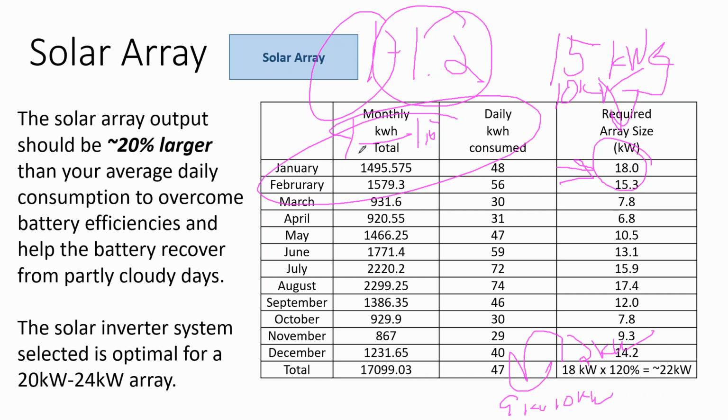And so, substantially, unlike with a batteryless system where the solar array is about 20% larger than the inverter output, on a battery system, the output may be 50% undersized instead of 20% undersized.